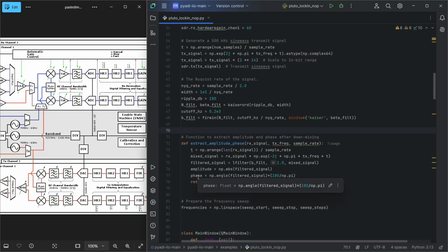So we need a mechanism to lock the phase, meaning that by using some synchronization, we know exactly when to read the ADC data, or when the sequence starts, and we start reading from that exact time. We will cover this in our next videos when we go to some advanced modulations like QAM modulation, which need the phase information.